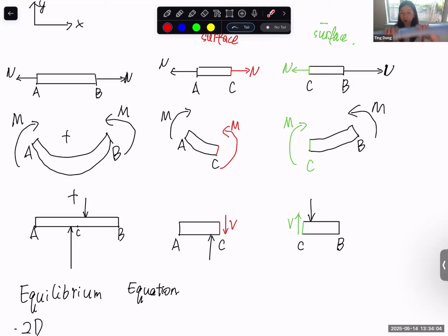And the same thing for bending. We talked about that. This is very consistent in all of solid mechanics: bending upward is considered positive bending. So again, we check this surface. This bending moment should bend in this way. But on this surface, it bends in this way for the positive bending moment.